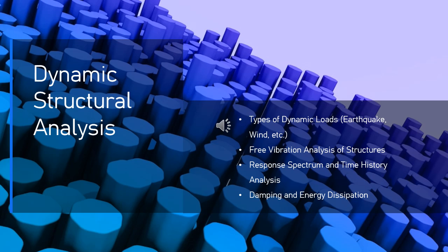Key features of time history analysis. Time-dependent. Unlike RSA, it provides a time-dependent response of the structure, which means it tracks the entire dynamic behavior of the structure throughout the loading event. Detailed information. It provides more detailed information about how the structure responds over time, which is essential when studying complex events such as earthquakes or impacts.